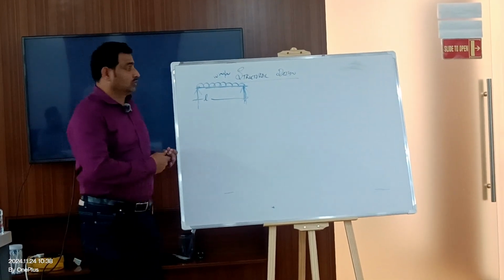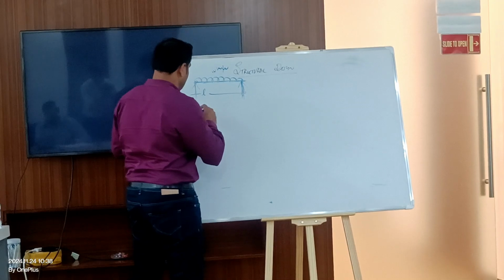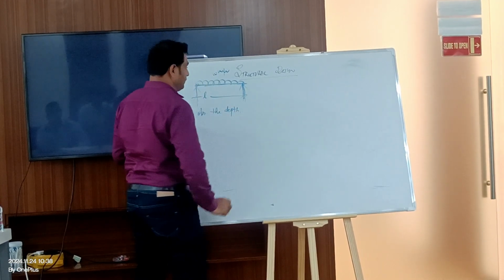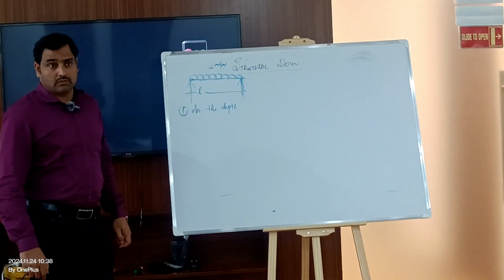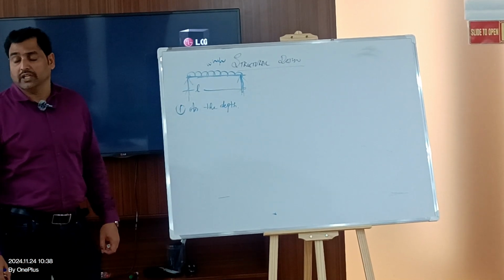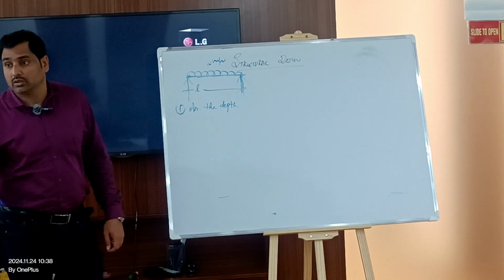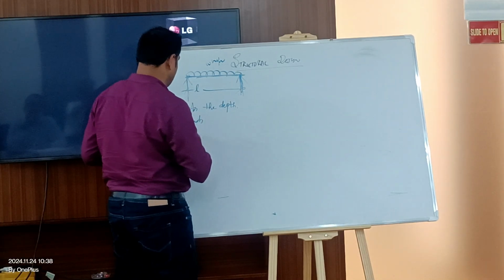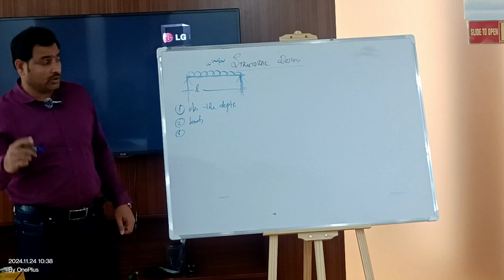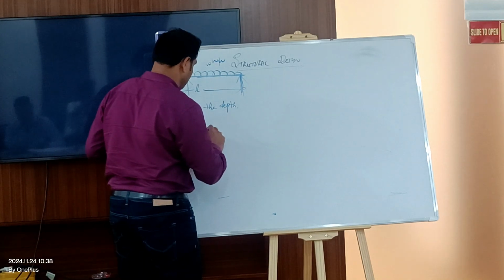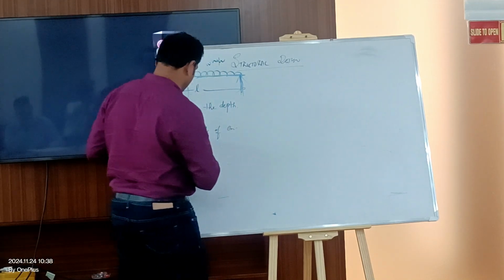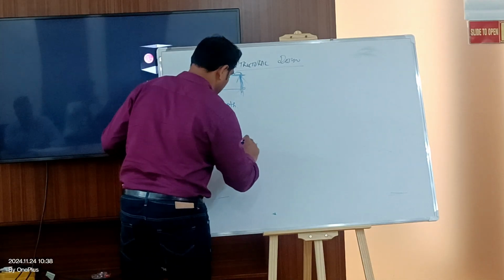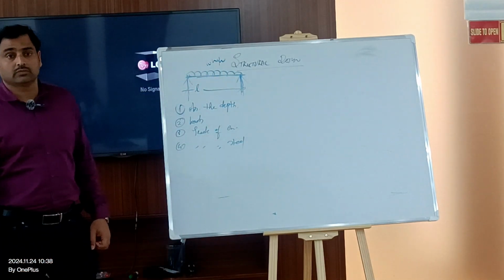First we count. Assume the depth. Span by 20. Assume the depth. Anything else? Loads. Then grade of concrete. Then grade of steel.